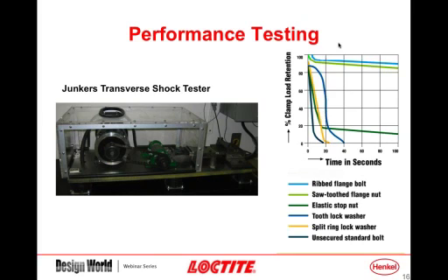It's when you get into the severe ribbing that we had on like the sawtooth flange nut that you can see that increase in the friction is probably the most effective way of mechanical devices to prevent the loosening. It does actually retain a fair amount of the clamp load. So those are traditional.